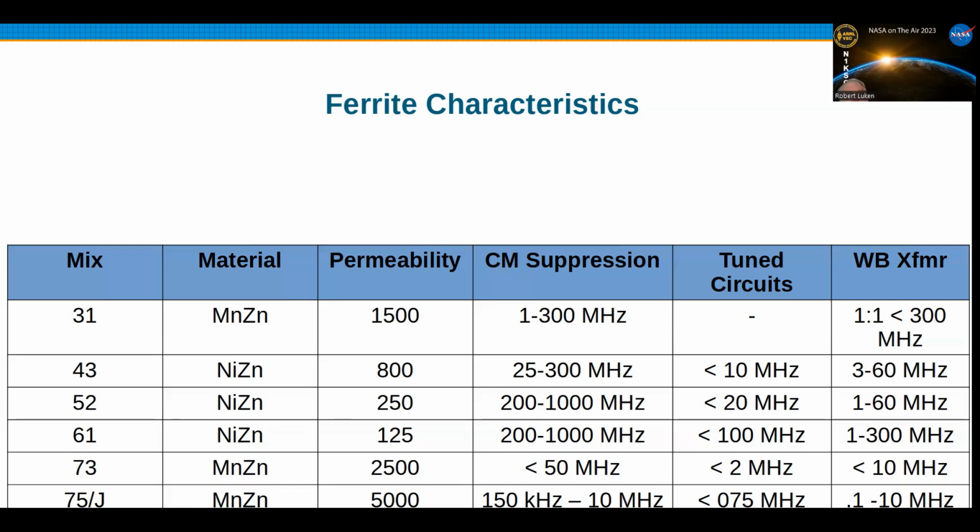Permeability is a multiplier of those other factors, the turns and the diameter basically of the coil, because more area is more inductance. You would think maybe a smaller one would, but larger diameters give you more inductance because you got more of a magnetic field, you got more wire.